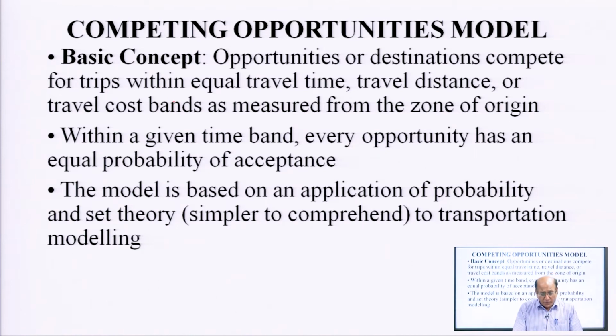Now, the competing opportunity model. Basic concept: opportunities or destinations compete for trips within equal travel time, travel distance or travel cost bands as a measure from the zone of origin. Within a given time band, every opportunity has an equal probability of acceptance. The model is based on the application of probability and set theory, similar to the comprehension applied to transportation modeling.